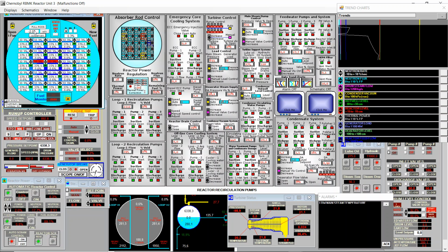And we see here this indicator, -2, this in a log scale. So if it's like -10 or -20, we can consider the reactor is shut down. Thermal power is still 0.3% because of the decay product. So we'll need some systems to cool this down, even if it's from a neutron standpoint a shut down reactor. The turbine is below 1000 RPM, so very close to total stop. Control rods are at 40%.